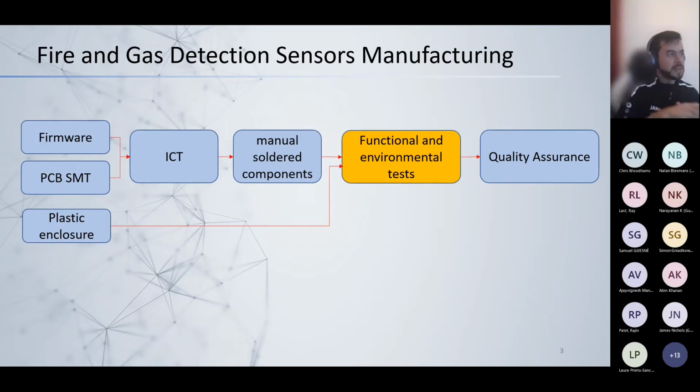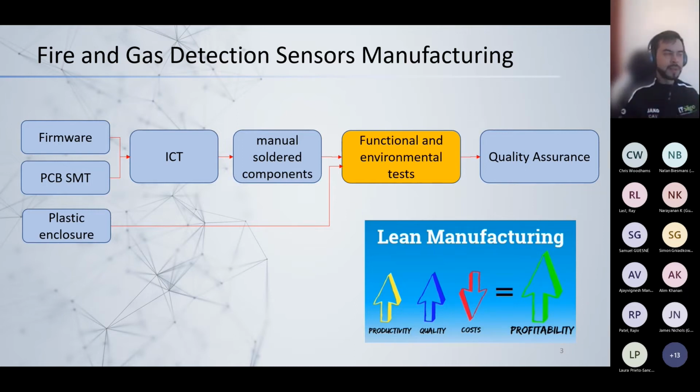And here's basically the idea, how they work as lean manufacturing. The base of lean manufacturing is to make the process in a smaller footprint, but covering many more features. We do SMT in-house, then we go for ICT, the in-circuit testing, and then we go for individual stations, some manual work, and then some automated and semi-automated tests that we call functional tests.